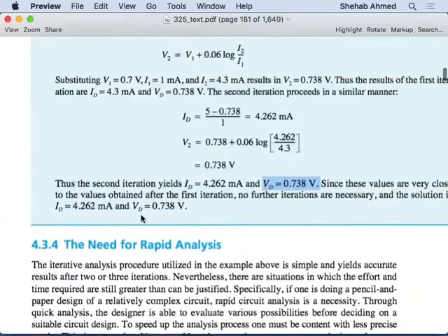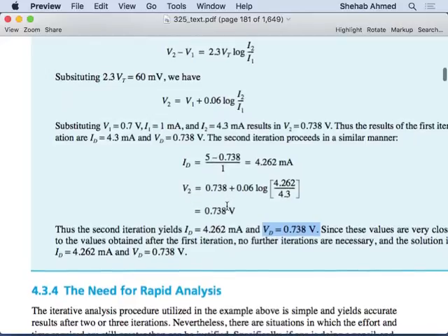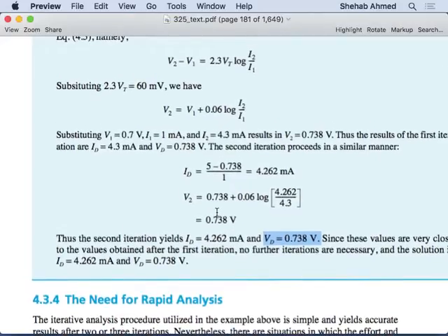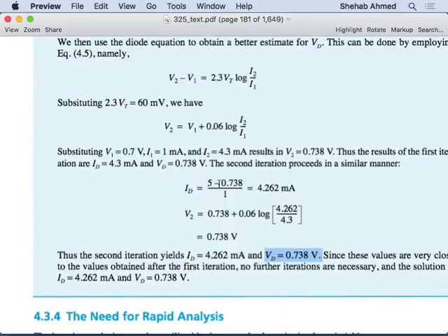You can continue. You will probably tune it a little bit. You have V2. You can take this voltage and plug it back into the current equation in VDD minus... You already did it. So you'll go back to the V2 minus V1, where V2 will be 4.62, the one you want to calculate, and V1 will be 0.738.